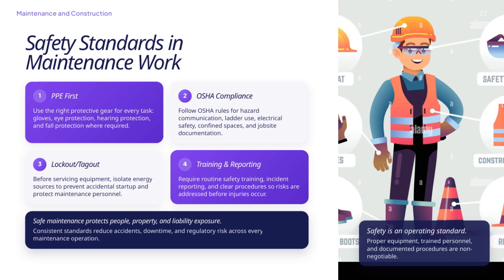Another critical practice is lockout-tagout procedures. Before servicing any equipment, it's vital to isolate energy sources to prevent accidental startups that could cause serious harm. This step protects both the person doing the maintenance and the equipment itself.